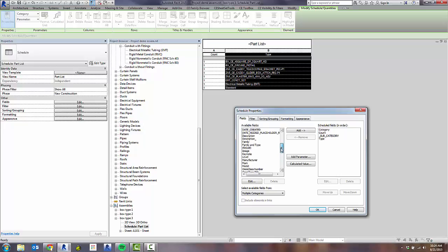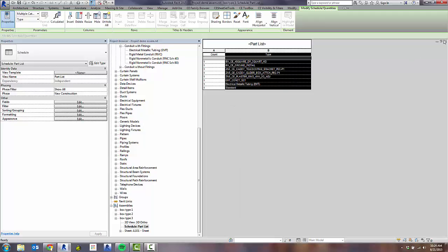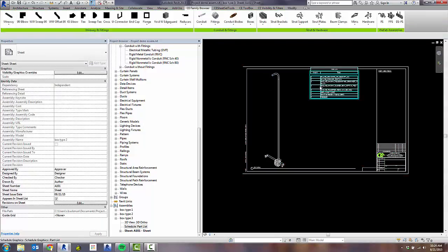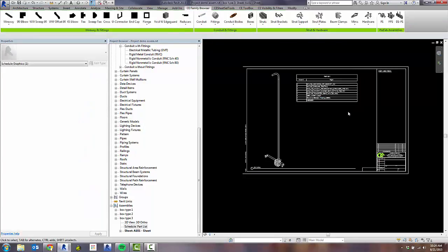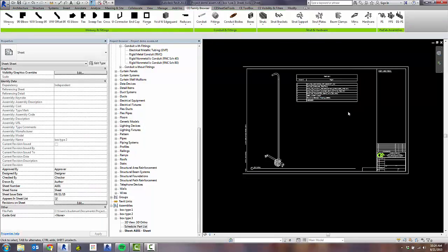Don't even see diameter listed in here for the system family stuff. So you're gonna have to use the comments feature that I showed you on the last one, since it's not really favorable to use a system family conduit if you're wanting to get the data, unless you go and pre-program that data in there.